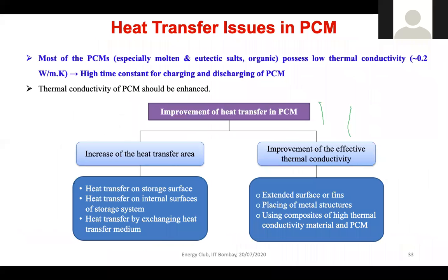Because of certain issues in phase change material, when you design this container we have to keep certain things in mind. One is how we can improve heat transfer between the heat transfer fluid and PCM, and within the PCM also. There are two broad methodologies we adopt. One is we can increase the heat transfer area, and the second is we can increase the effective thermal conductivity of the storage.